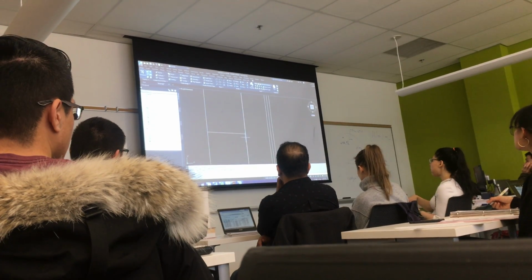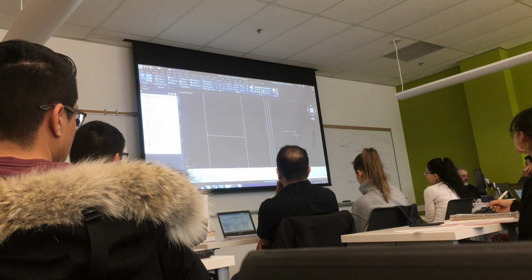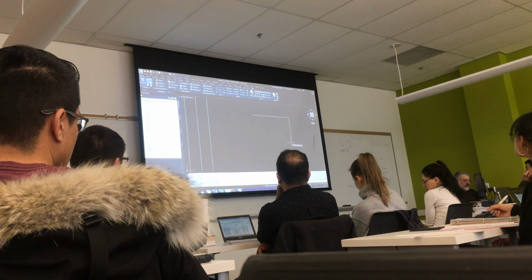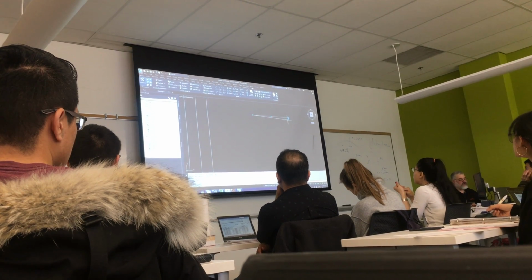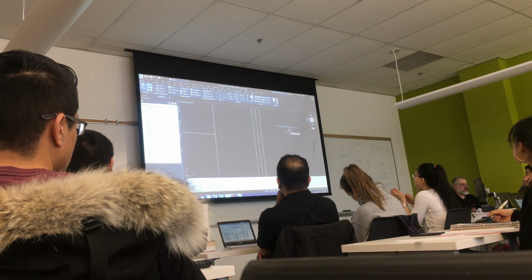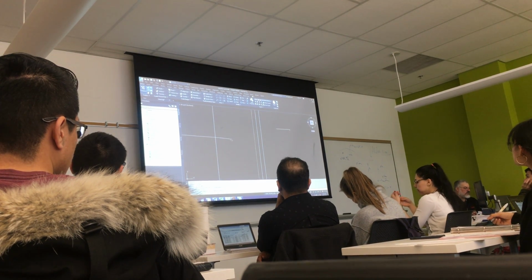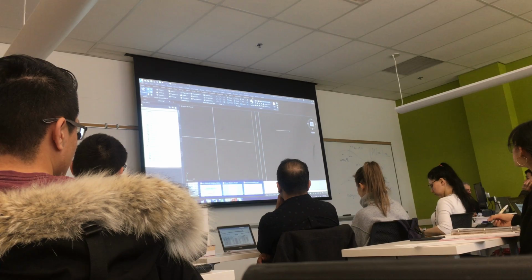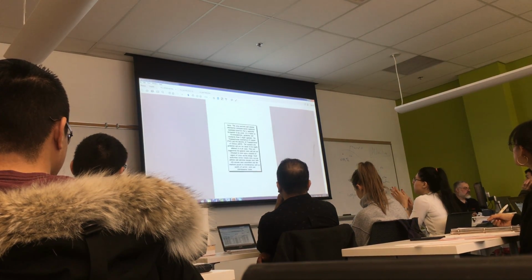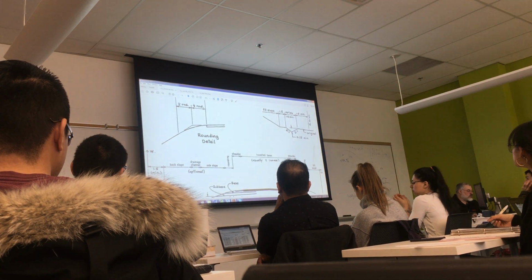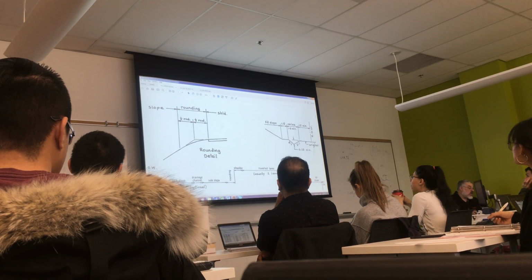The plane for the shoulder is 6%. So I'm going to go horizontal 1, 0.06. Close. There's 6%. 1 meter horizontal, 0.06 vertical, and there's my angle for 6%. Put it on here. Extend it the width of the shoulder, but if you remember, we go back to the detail on the first page. The plane of the shoulder goes to the middle of the rounding. So extend it to the shoulder and beyond to the middle of the rounding.